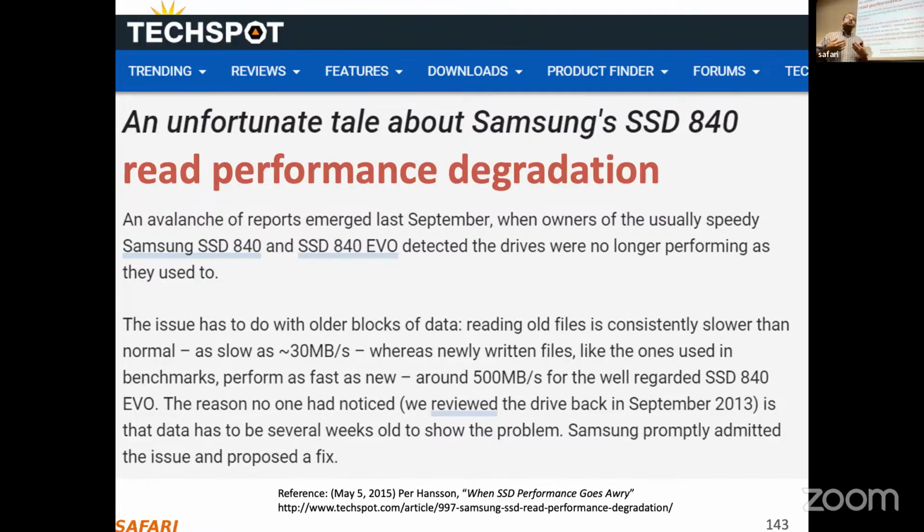And you will see that basically the read latency is going to increase by 10 times. Because in the past you had only one read access, but now, because of the ECC errors, you are reading your data 10 times or even more. And that's essentially one of the reasons why SSD or flash chips are getting slower and slower.